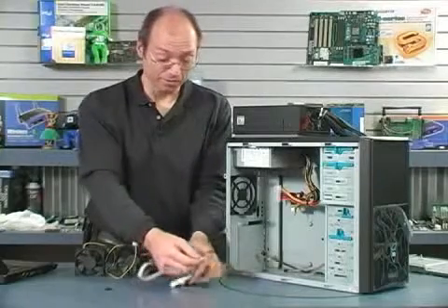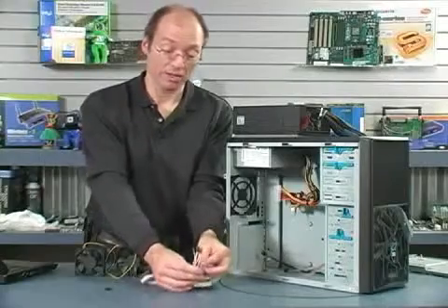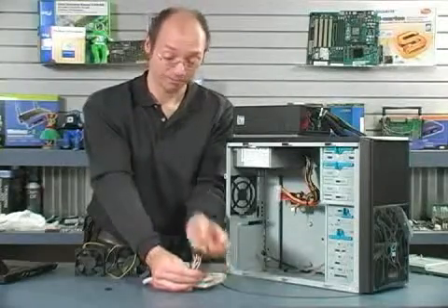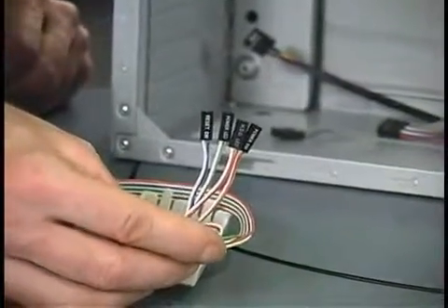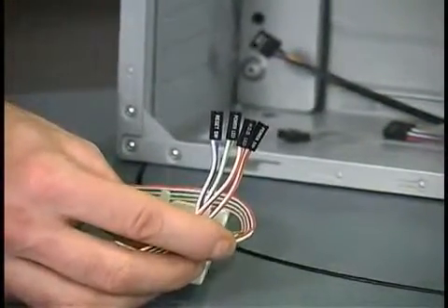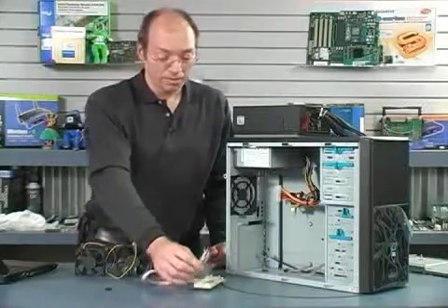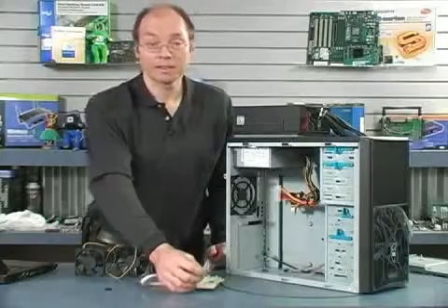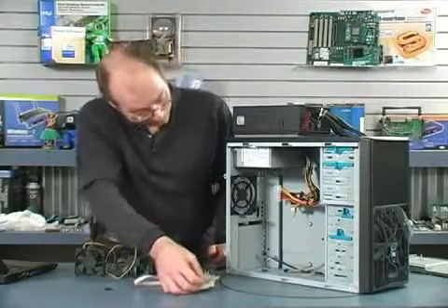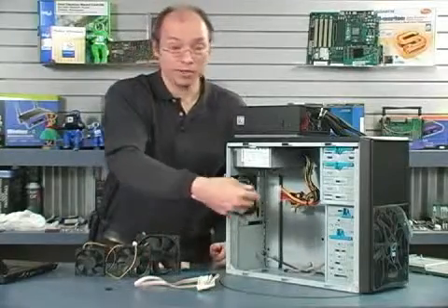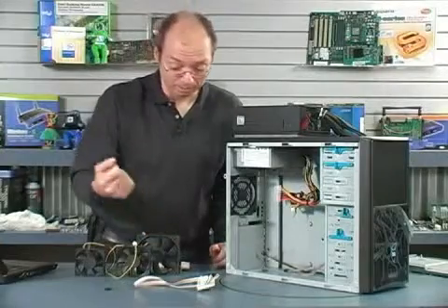Well, if you've ever built a PC, I'm sure you've seen these, you have these 4 different connectors. They're 4 little 2-pin connectors. And some of them are polarity sensitive. The ones for the LEDs have to be in the right polarity or the LED won't light up properly. And it's easy to miss pins. Plugging these in is the bane of PC builders everywhere. It causes no end of trouble. You can't see what you're doing, because you have to do this with the motherboard already installed. You can't do it with the motherboard out of the system.